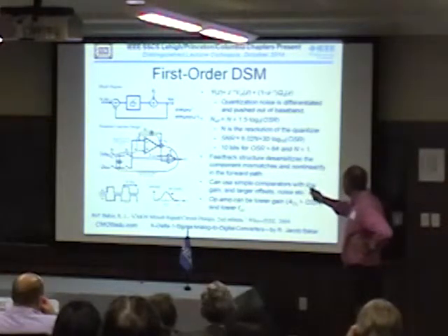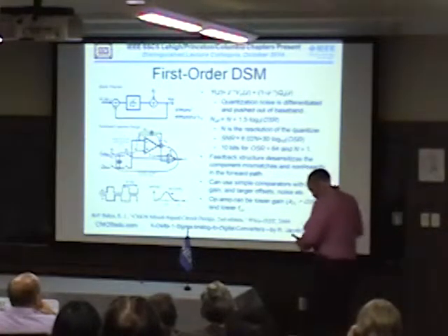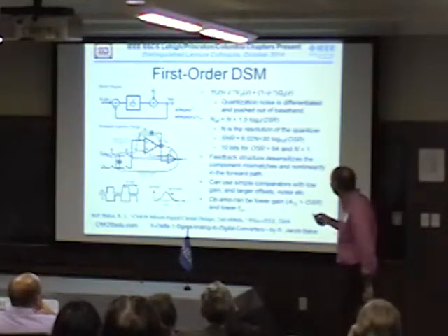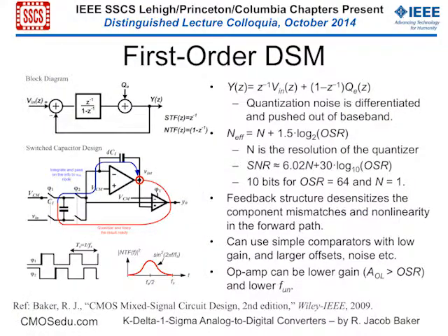Now, and I'll show you this on the next slide. Before I do, actually this might work. I have to use this one, I'm going to run the battery down. So here's the Z domain representation. The total output's here. So the input is delayed by 1 clock cycle, so it goes to the output. That was in the previous slide, that was this thing. And Z -1 is the phase shift, 1 clock cycle. And then this is a differentiator, so it differentiates the quantization noise.